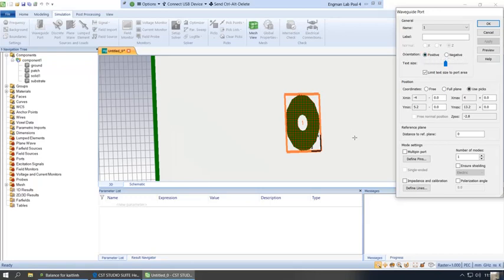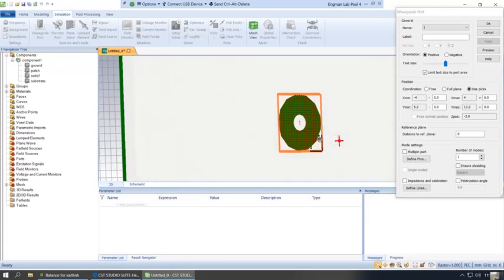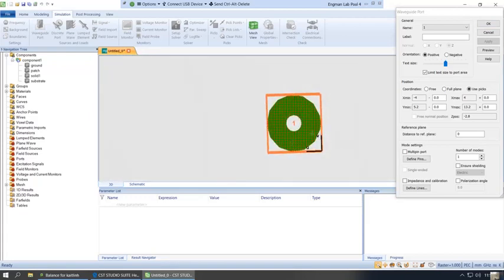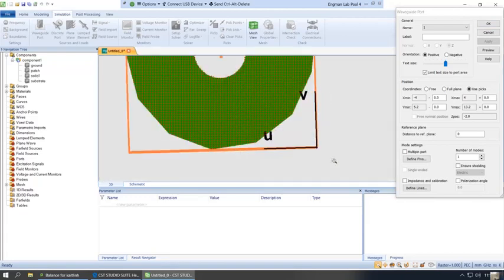So it's difficult to see in this picture, but if we rotate, again, hold down Control and left click, we can zoom in here and we see that there is this vector. And you can't see it, but what it's trying to show you is that it has defined the direction of propagation in the positive direction right now, in the positive Z direction. And in our case, that's what we want. That's the direction of excitation to excite our patch antenna.